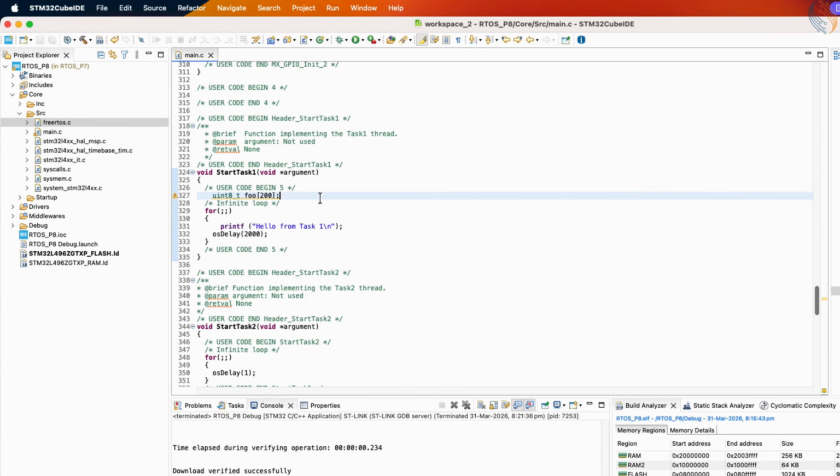This situation perfectly highlights the real danger of Stack Overflow. It doesn't always cause an immediate system fault or crash. Instead, it can silently cause data corruption in adjacent memory areas and create unpredictable behavior throughout your system until the corrupted memory is actually accessed or used by the processor. This is why early detection is so critical.